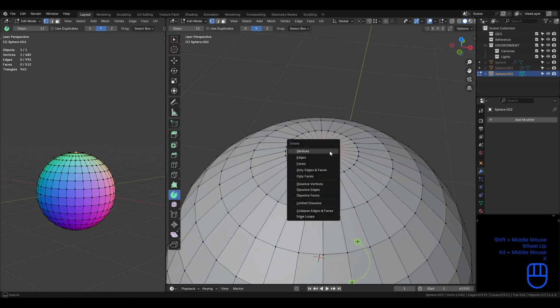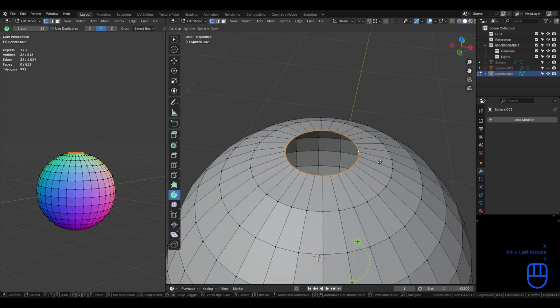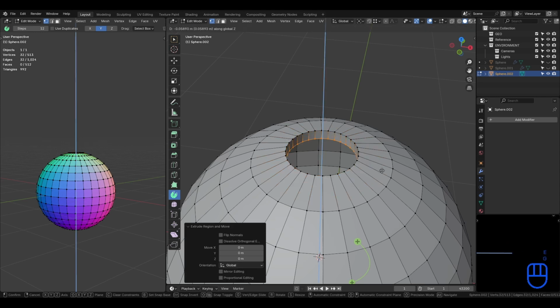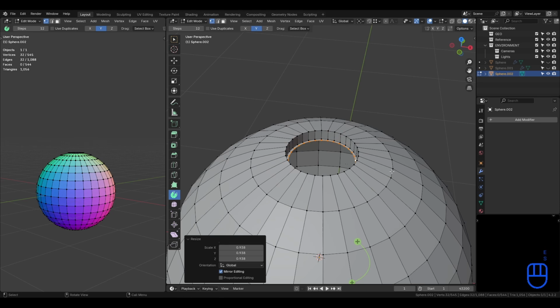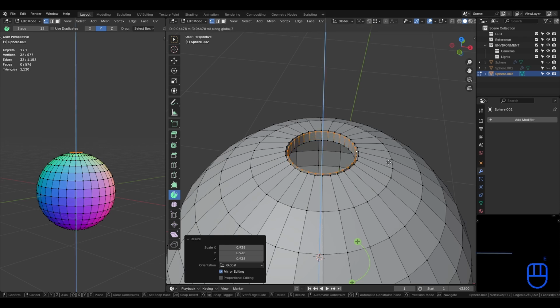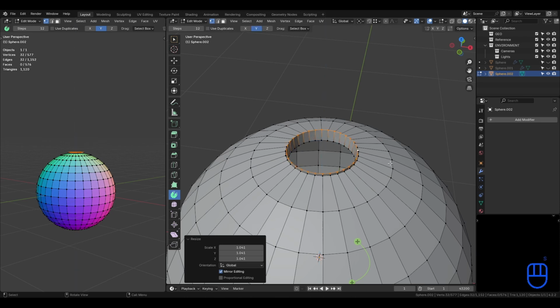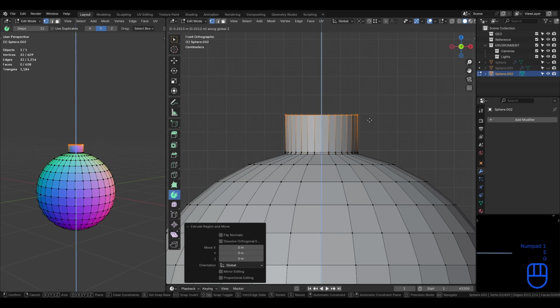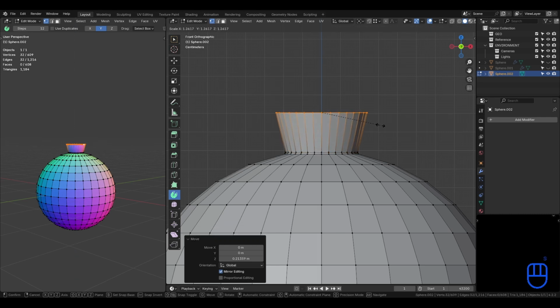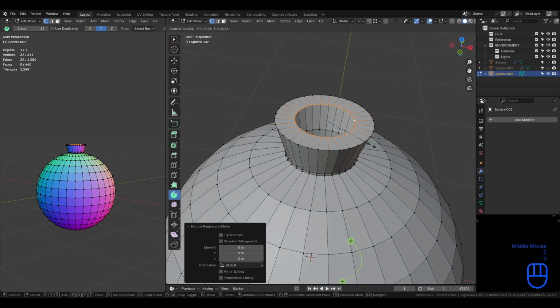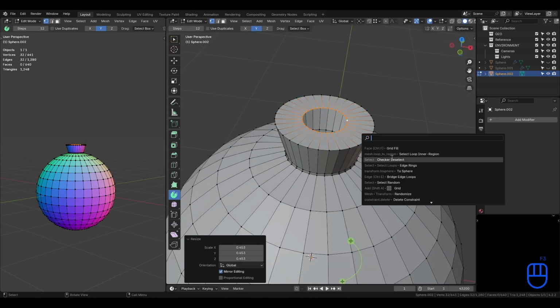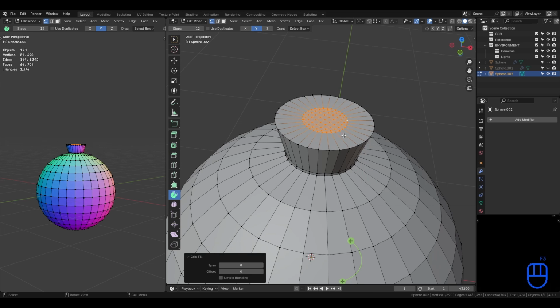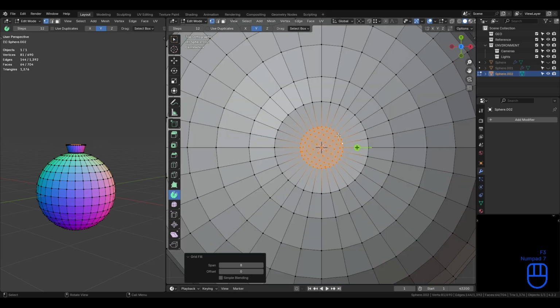First, remove the top vertex of the sphere to create an open space. Then use extrusion to shape the cap gradually. Do a small extrusion as well to add detail. And finally, use the grid fill to seal the top neatly, and if your grid fill result is not aligned with the other vertices, you can rotate the grid fill through the pop-up menu in the bottom left corner.